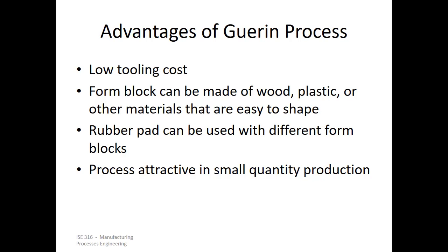Form blocks are easy to shape, and although the form block is changing, the rubber pad need not change, so therefore you have less changeover in the setup, right?